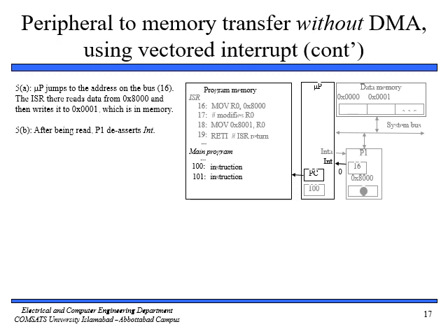Now at step 5, the microprocessor jumps to the interrupt service routine. So the microprocessor will jump here. Now after going through these 3 instructions, it will read, here it is reading, here it is modifying, and then finally it is moving. So we need to correct this. This is not 0x8001, rather it is 0x0001. So this is a mistake here.